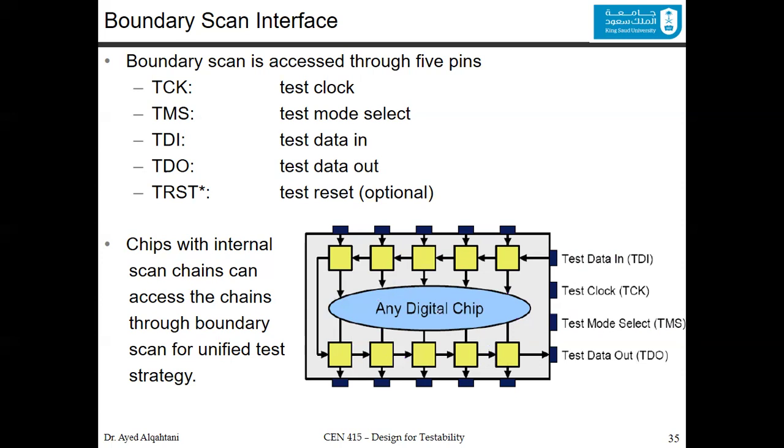And then you work on the test. You have to switch to the normal mode. And after that, you get the values within the pins after you finish the test and shift them out by going again to test mode and entering a value of 0 just to push the values outside and check if you are getting what you expect or not.